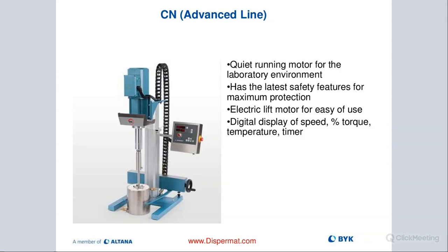It's 2 buttons on here where you just lower the blade to the desired height, bottom height, push H2, then raise it up to the top, and then press H1, and that will lock these 2 threshold settings in, and you'll be able to then run the Dispermat safely.